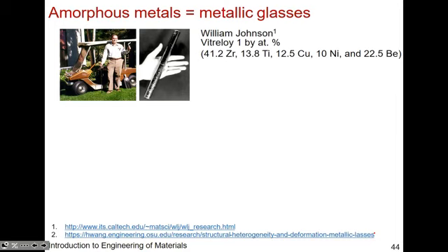You don't want phase separation. You want it to be one homogeneous phase, right? And so the way you do that is when you're solidifying, you just drop the temperature really fast. And when I say really fast, I'm talking about like 1,000 Kelvin a second. Can you imagine cooling anything that quickly?